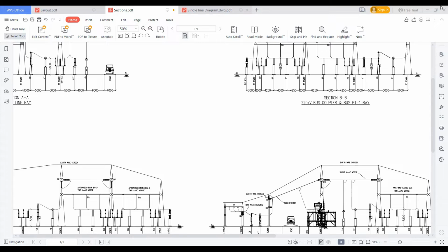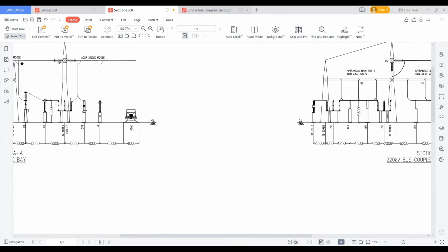In Karnataka regions, you can see this isolator is here, right? These isolators can be placed like this. I mean, they are underhung isolators. They will place isolators like this, and instead of taking this CT from here, they will take all the CTs before, and they will take that connection like this. Underhung isolators are restricted from use in Andhra Pradesh and Telangana projects. So it totally depends on the project, on the utility.